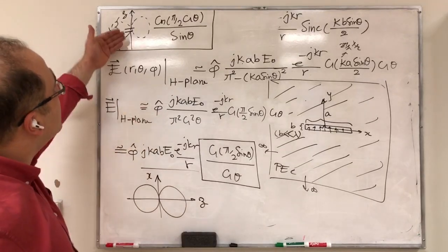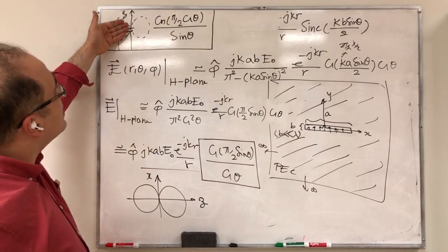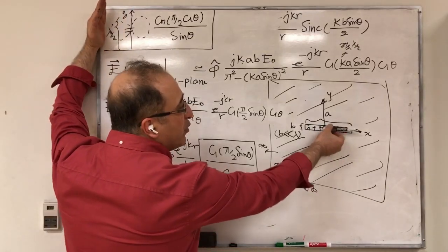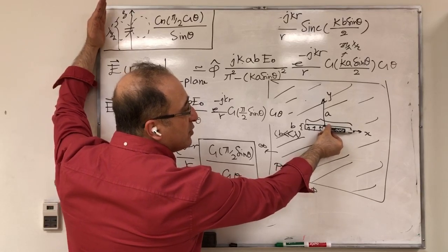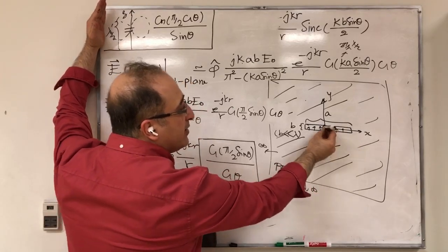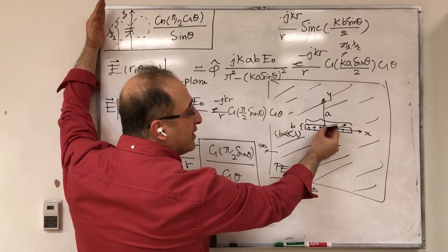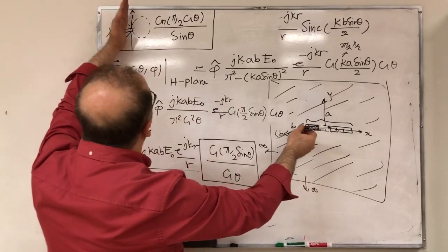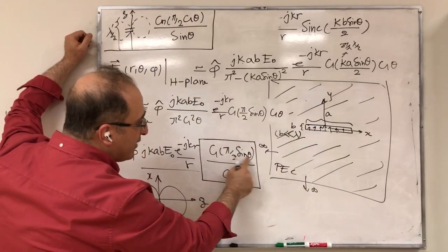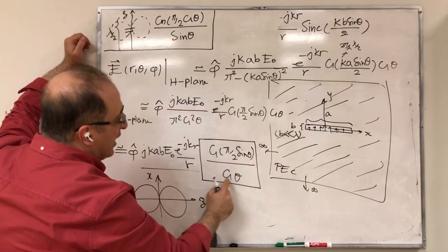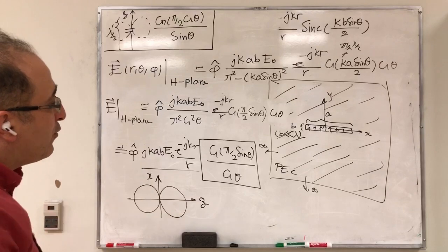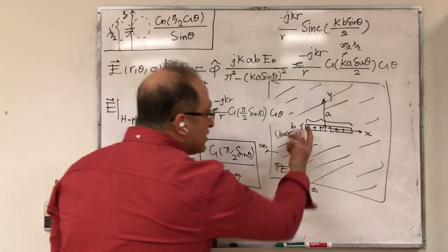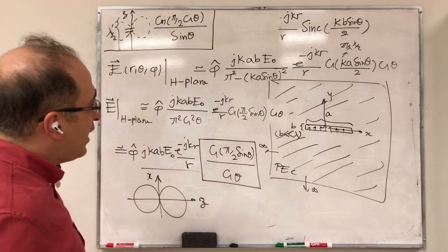So theta equals 0 in this case, which is along the Z axis, is not going to be the same for this, because now the axis is actually the X axis, which is theta equal 90. Remember, this is Z, so you go theta 90, you get to the X axis. So you see there you have a 90-degree phase shift between your axes here. If you apply that 90 degrees, your sine becomes cos and your cos becomes sine, and therefore they're actually the same thing. So the point here is that you see how closely this relates to the dipole antenna.